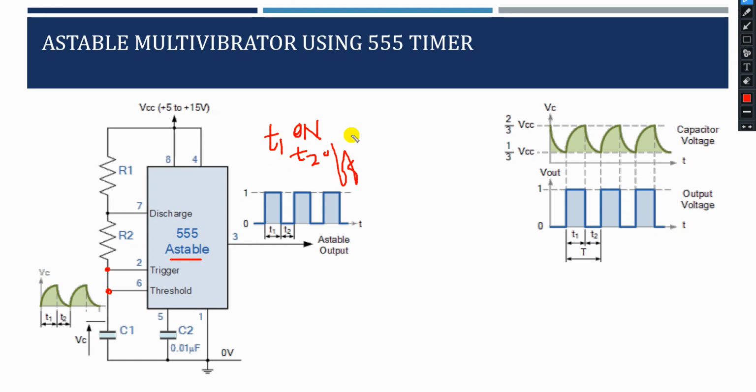So in the 555 oscillator circuit, as we have seen here, pin number 2 and pin number 6 are connected, we know that. Allowing the circuit to re-trigger itself. So it will re-trigger itself on every cycle, allowing it to operate as a free running oscillator. So it is an oscillator, it is generating some pulse. It's a free running oscillator. Because 2 and 6 are shorted, it will start triggering itself by T on, T off, T on, T off, T on and T off. This will continue.